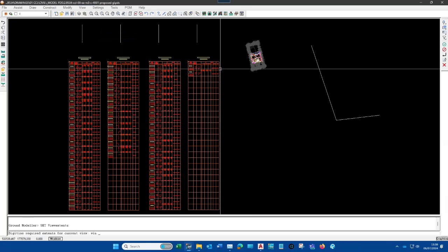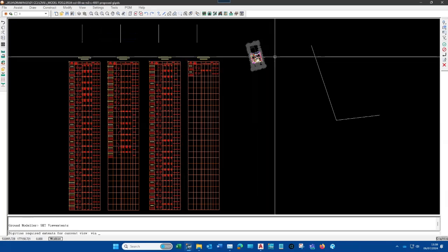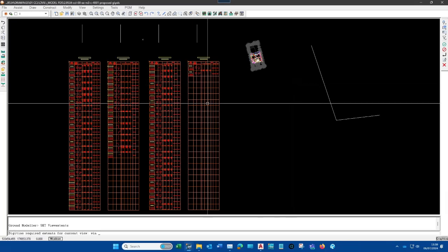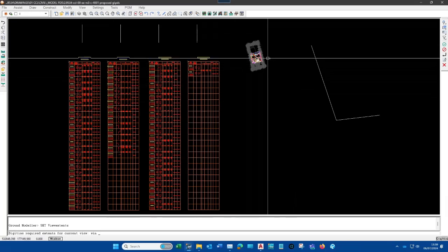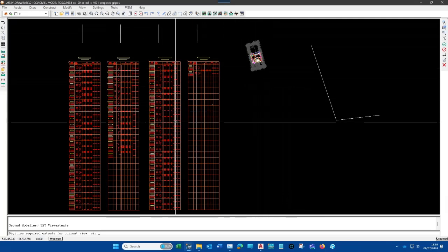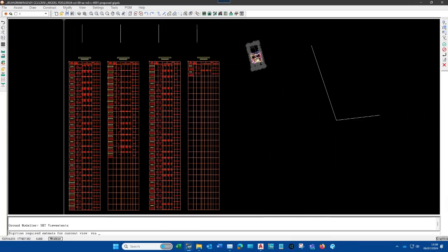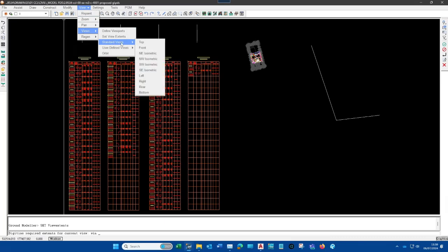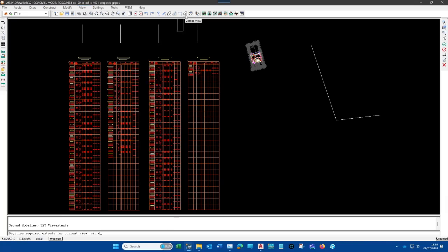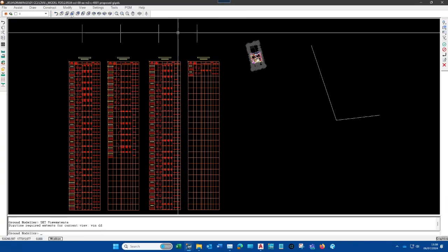You can set view extents, so you only have a perimeter of when you go zoom extents instead of doing the whole thing, which might be good because zoom extents will be the site rather than viewing everything like all the profiles and manhole schedules. But we'll go into this one, which is these are standard views, top, front, left, right, and such. And if you go into this button, change view, you have top, bottom, front, rear, left, right.